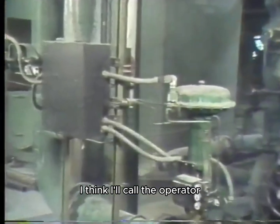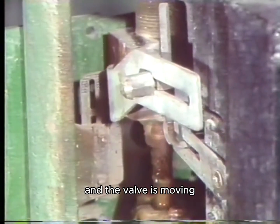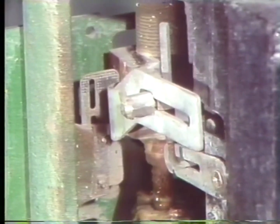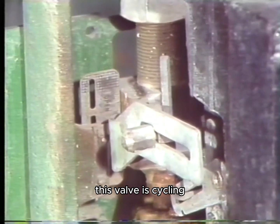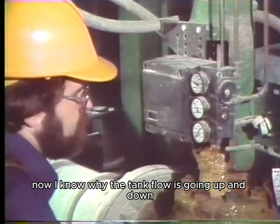I think I'll call the operator and have him put the system on automatic, see how it responds. The controller signal is increasing, and the valve's moving. Uh-oh. Now the valve's closing. This valve is cycling. Now I know why the tank level is going up and down.